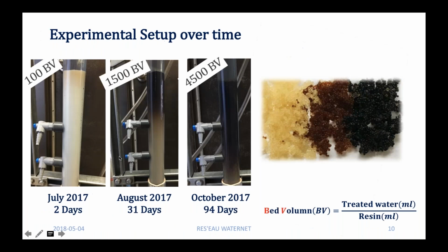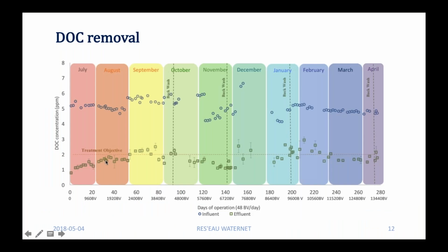Maybe here. At first we didn't do backwash because the pilot is not here, and the operator there was not trained to do the backwash, so I needed to do the backwash when I traveled there. In the first 3 months, I didn't do the backwash because we were using filtered water, and we didn't see any evidence of clogging or accumulation in the columns. But after a while, we needed to do the backwash. So every time that I traveled there, I did a backwash. Did I answer your question?